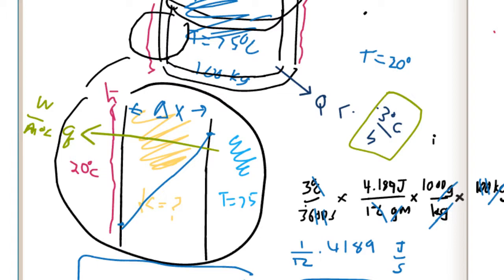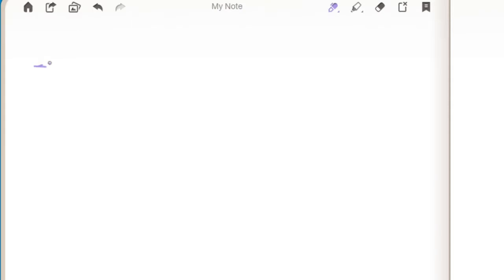Okay, so the initial steel wall is a single resistor, and I'm going to pick a different color here. So this wall is a resistor, the insulating material is a resistor, as this steel wall is a resistor, and then the convective wall is a resistor. So these are resistors in series, and we'll find that this will be a good assumption if pretty much all the temperature drop occurs over the